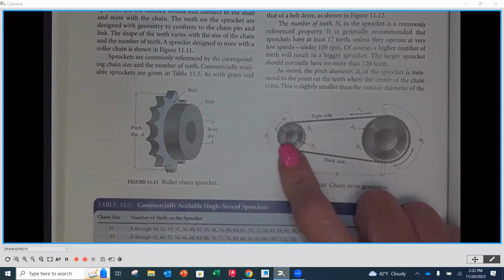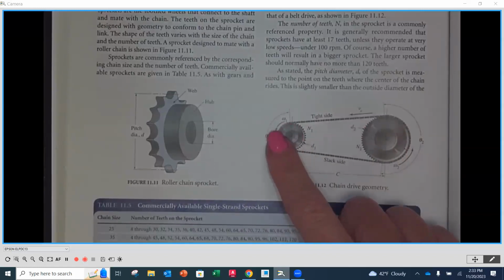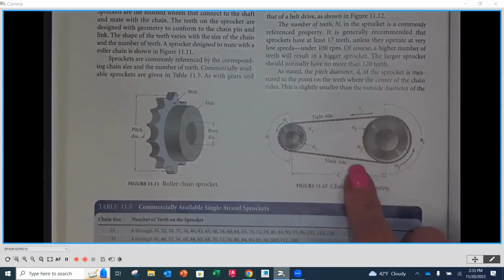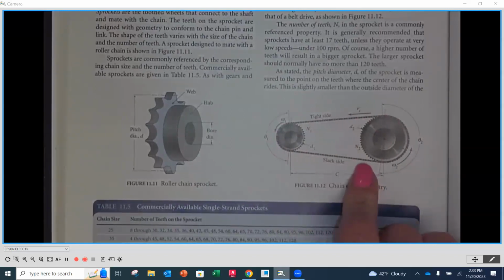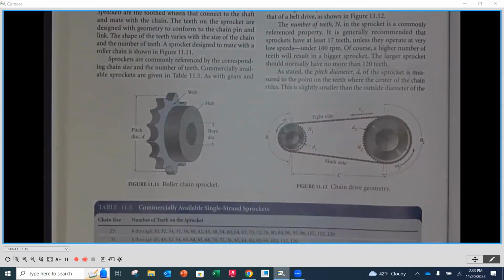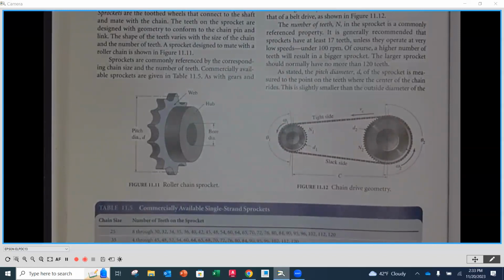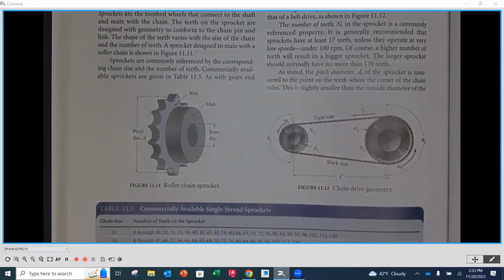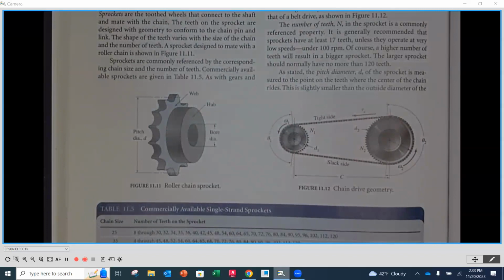So kind of the opposite of what we saw earlier with the belt drive. Since it's going counterclockwise, that means it's pulling this side along, and then your slack side is going to be on the bottom. That's actually the preferred arrangement. Why do you think so? To make sure that your slack side is on the bottom. For a chain drive, oh, go ahead, Eric.